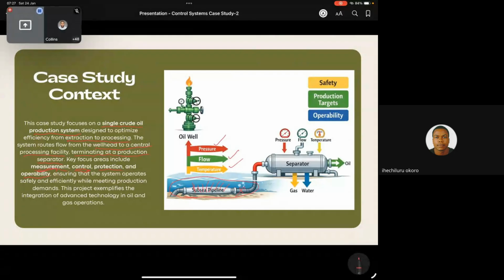It needs to control, because what if there is an incident around here? Let's assume that there is fire here. I mean, at the very basic level, if there is fire in this environment, the first thing he wants to do is to be able to cut this supply, so that at least there will be no crude coming into the separator.